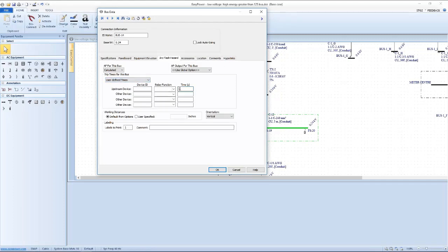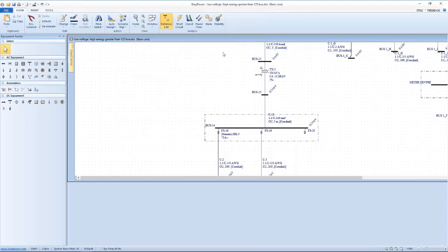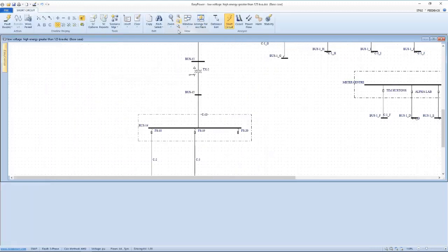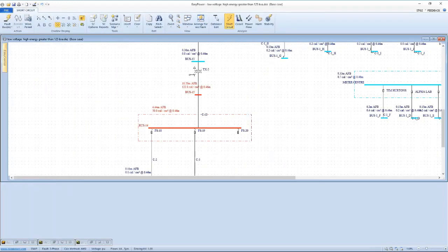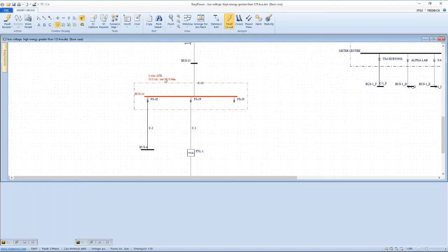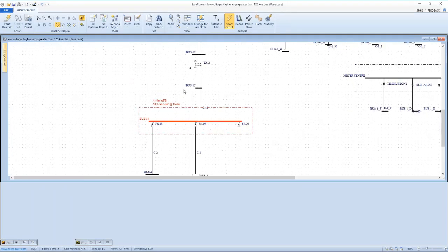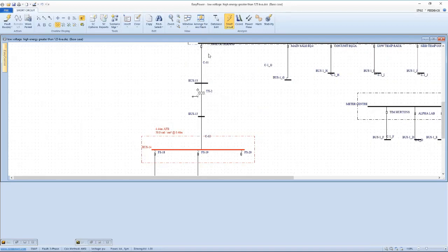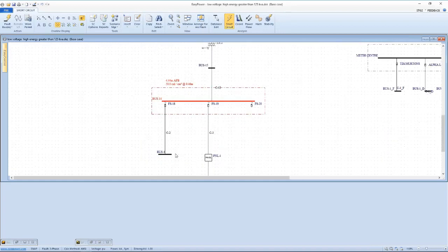We'd apply 2 seconds as a maximum calculation time based upon this bus. And even with that, we're looking at a potential 50-calorie calculation. So the issue here is the fact that this is probably an older installation, and we have a primary fuse protecting a remote device, and it's not adequate.